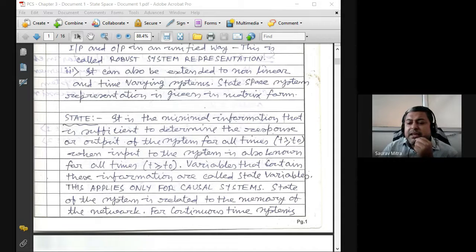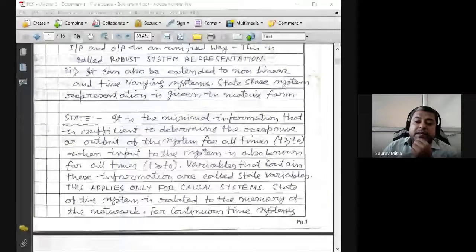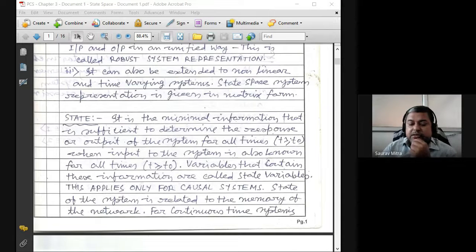So you are finding there are 4 parameters: resistive voltage, inductive voltage, capacitive voltage, and current. Out of these 4 parameters, any 2 you can take and say that these are the 2 states of the system. There is nothing else besides these 4. For an RLC series circuit, there can be a maximum of 3 voltages and 1 current. That current is i_L or i_R or i_T or i_N, whatever you call it: input current, resistive, inductive, capacitive, and that current can have an initial value also.